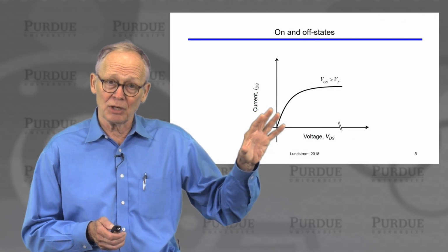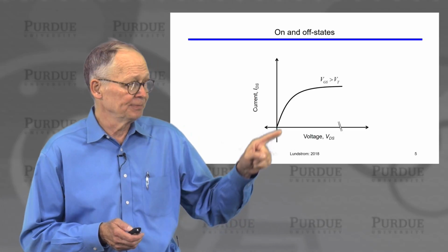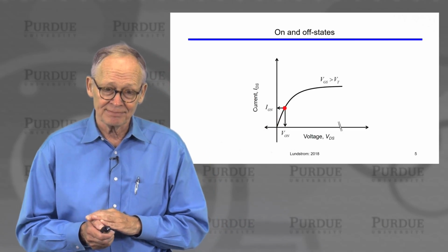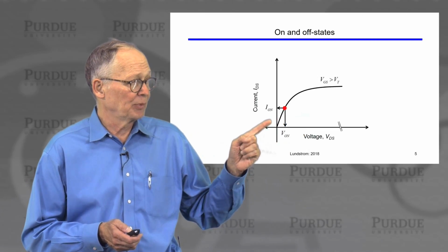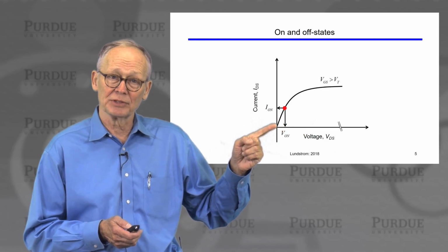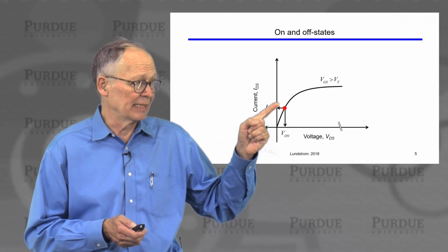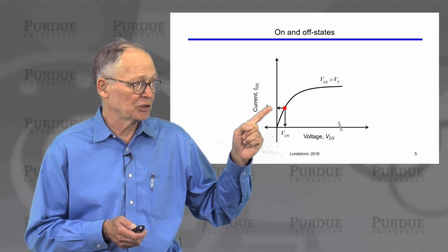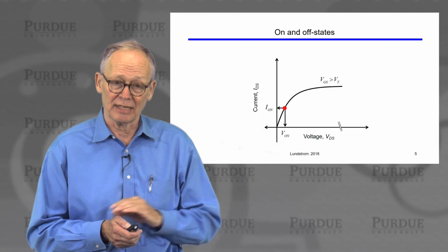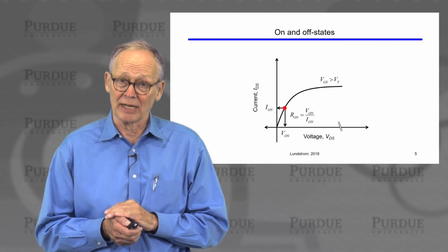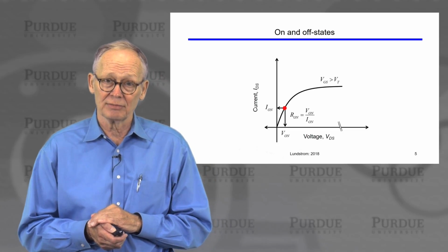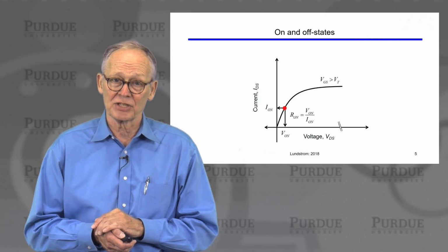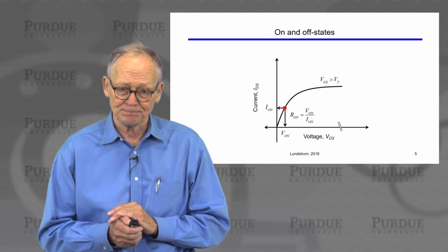Okay, so we're going to use the MOSFET as a digital on-off switch. MOSFETs have IV characteristics, output characteristics that look like this. We would like to be operating at some low voltage when the switch is closed and get a high current that flows. So the key considerations will be how much current flows at a particular on voltage, and we will be operating here in the linear region of the IV characteristic. The on resistance will be the on voltage divided by the on current.